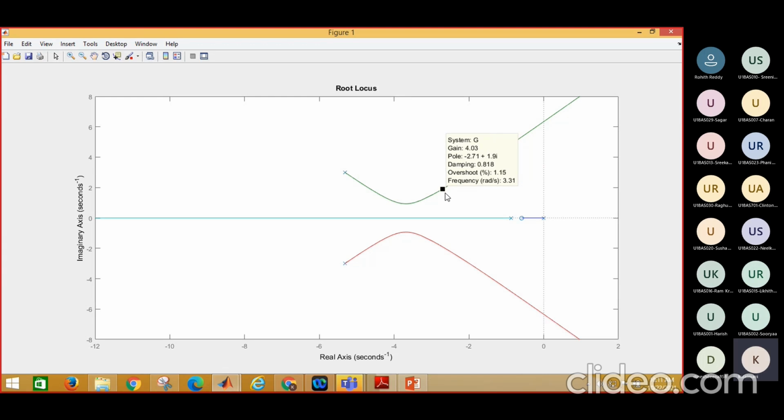So if you have higher damping in your inner loop, there is a tendency to pull this closed loop system to lesser damping. Okay, so if we increase the rate gyro amplifier gain value, my damping will be reduced. See here, my damping goes to 0.226 if I have a gain value of 13.9. Therefore, we need a slightly higher damping value, because if you have higher damping, then we have lesser overshoot. Therefore, we keep the damping at almost 0.7 or higher than 0.6.